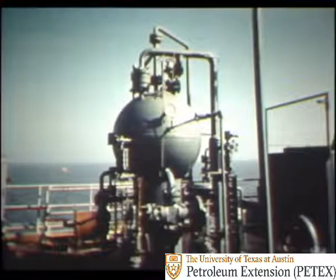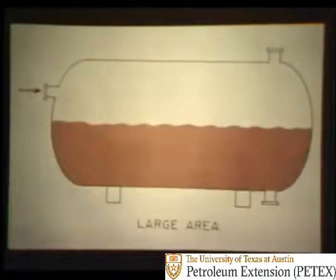From the outside, the separator appears to be only a tank with piping, valves, and instruments hooked onto it. There is, however, more than meets the eye, so let's begin by looking inside a separator. The production from the wells, which is a mixture of oil, water, and gas, enters one end of the separator. Upon entering the larger area, the well stream slows down and separation begins because of the difference in gravity of the fluids. The separators on your platform will usually have features like those we will now discuss.